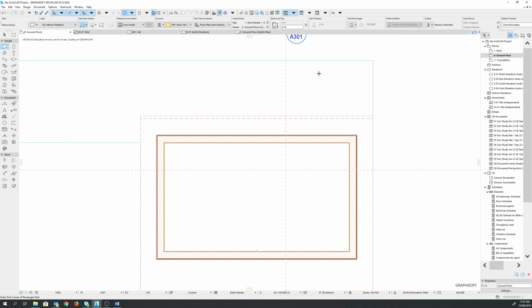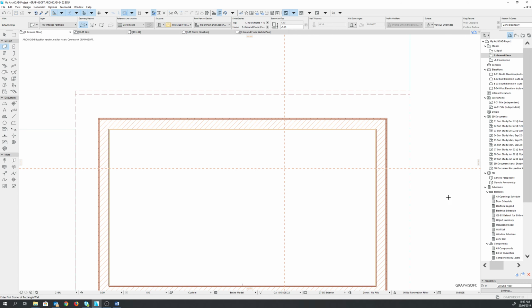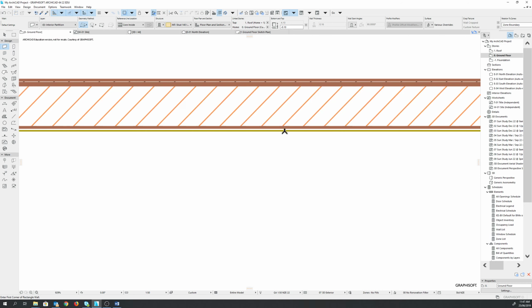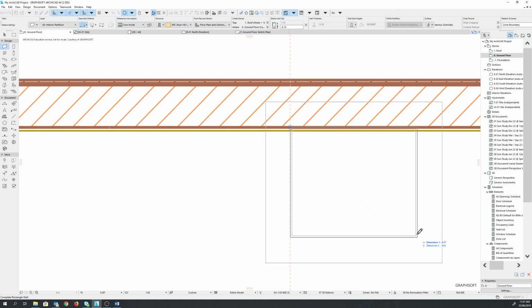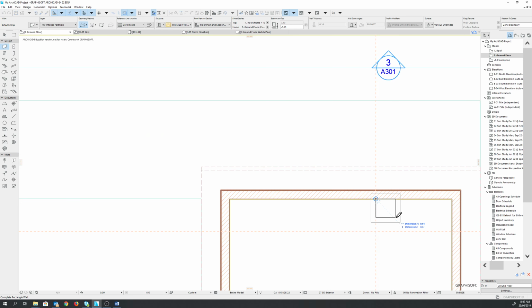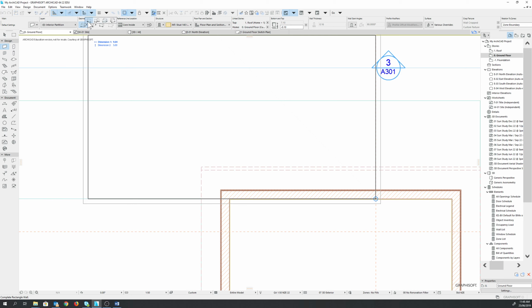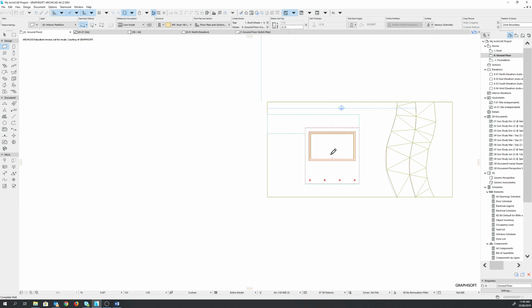So next thing we need to do is to draw now our walls on the guidelines that we have here. So start anywhere, you can either start down or you start horizontally, whichever way you want. So click the first one. Now you can see my wall is on the rectangular geometry method, so I'll need to change that. Go up to geometry method and choose the single, the first one. When you click on it, you can see it changes to single.